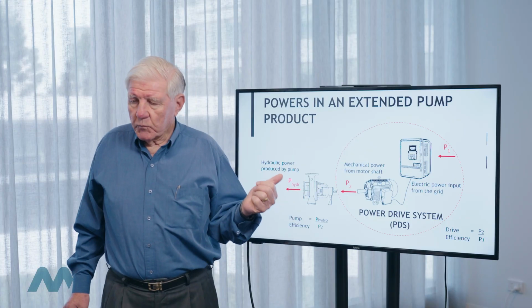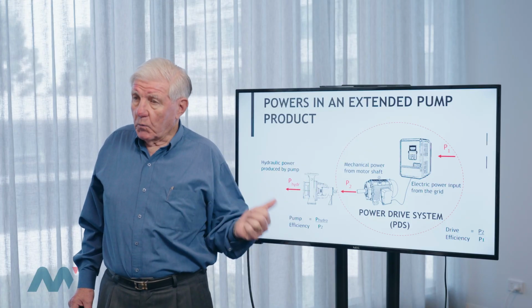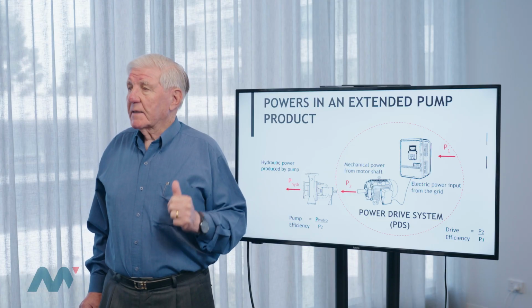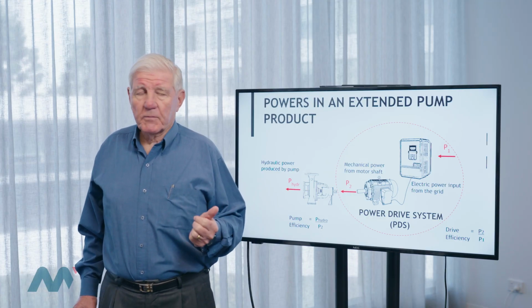So when you're looking at, do we have variable frequency drive or don't we have variable frequency drive, we need to understand a lot more about the system that the pump is operating in. For example, if we have a system where the pump is operating against a high static head, then generally speaking, throttling is a more efficient way of controlling the flow. But if you've got one that's got zero static, then variable frequency drive is a better way of controlling flow. And you'll find that in the HVAC industry, variable frequency drive is very common for controlling variation of flow rate.